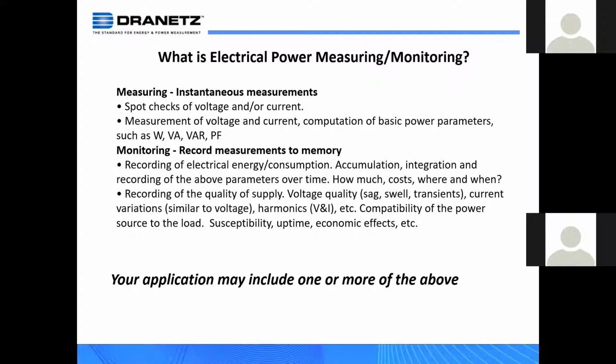When you use those similar tools and you have a power quality capable instrument, it's taking that same voltage and that same current, but it's looking at it a little bit differently. Think of it through a different filtered lens. So you're not looking at accumulation and how much, but you're buying that instrument because you want voltage quality. You're looking for changes in that voltage and/or current that can affect your processes, affect your quality of supply and whatever your operation does.